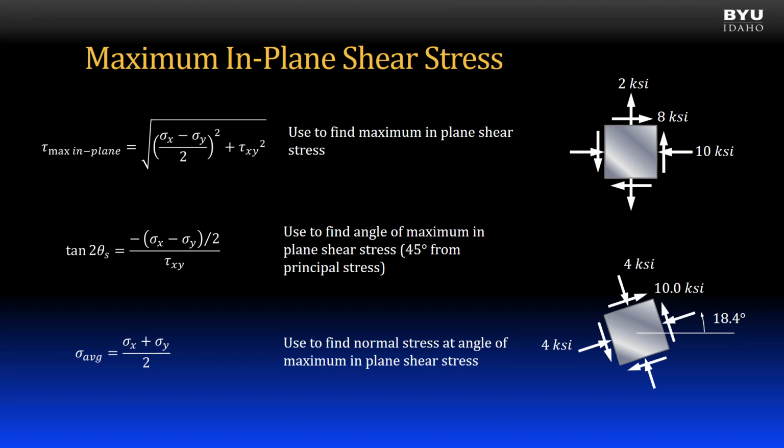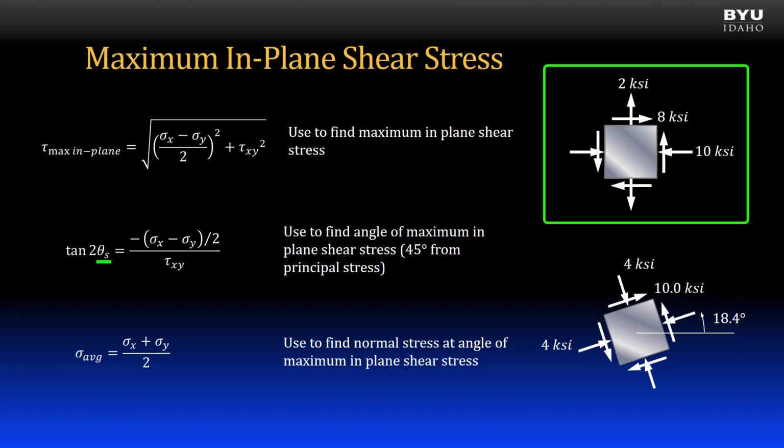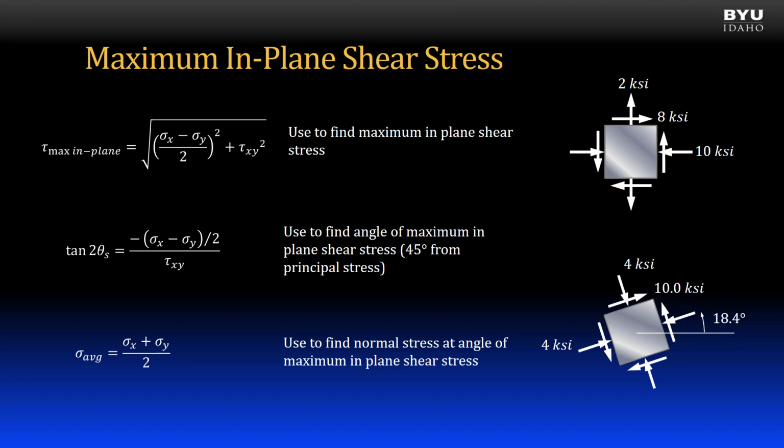I can input the angle theta s and the normal and shear stresses of the original element into the tau x prime y prime general transformation equation to determine the direction of tau max in-plane.